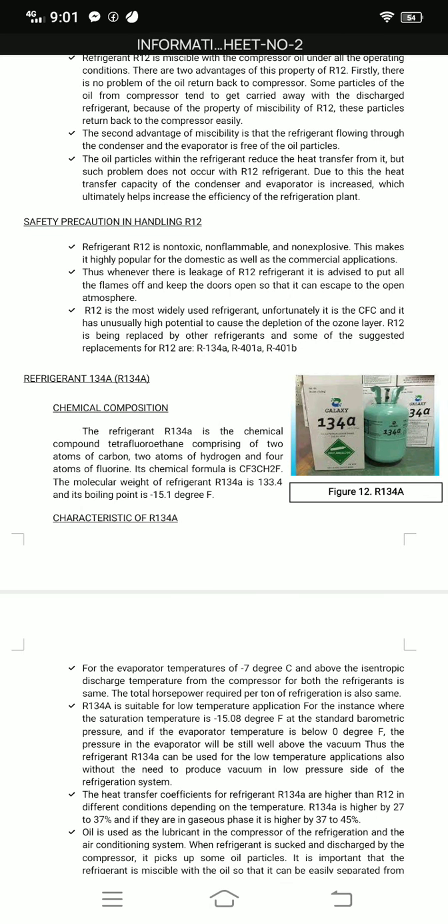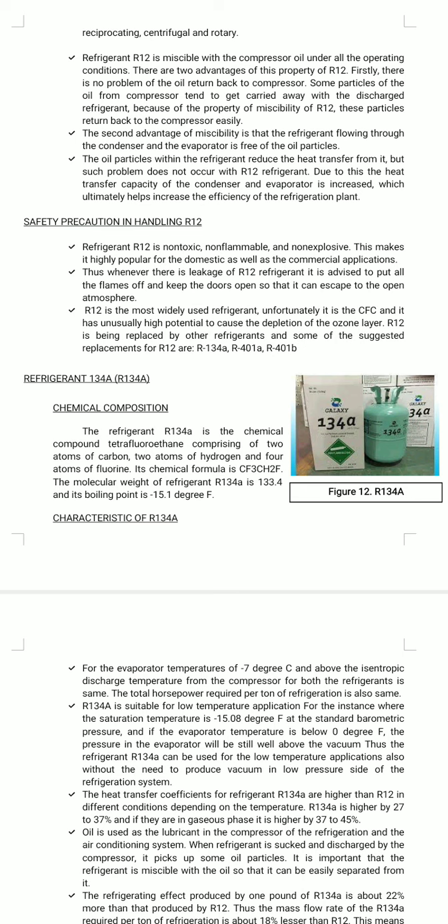R12 is the most widely used refrigerant. Unfortunately, it is a CFC and it has unusually high potential to cause the depletion of the ozone layer. R12 is being replaced by other refrigerants and some of the suggested replacements for R12 are R134A, R401A, and R401B.